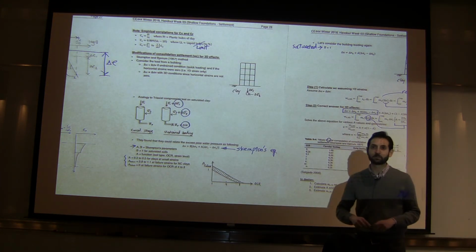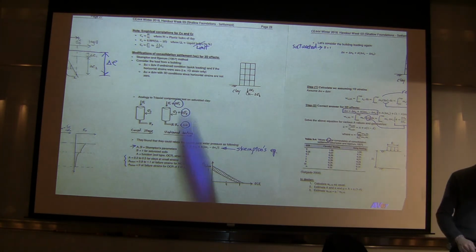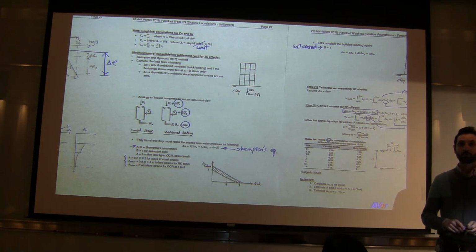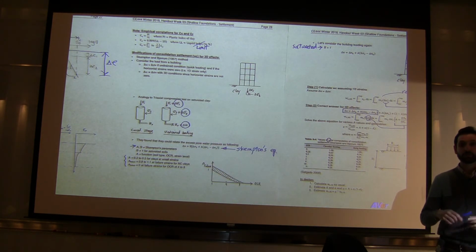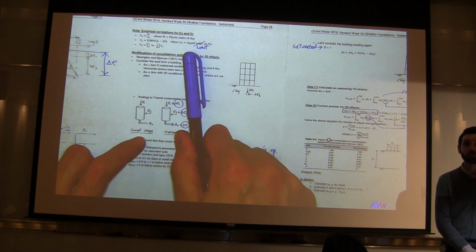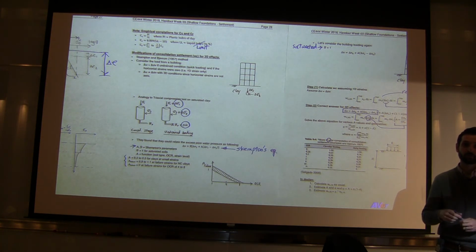In practice, sometimes people call it liquid index, but I like that you picked it up because we had another parameter called liquidity index, and I don't want you to confuse this with the liquidity index. Liquidity index, you're right, was a ratio. And this thing here is just a liquid limit. It's a water content, and it's in the form of a percentage.